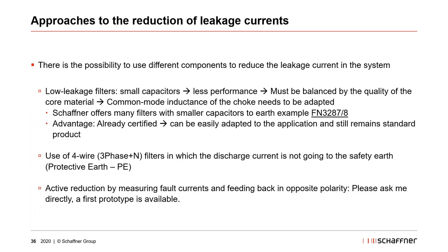Additionally, if you have the ability to use a 4-wire filter, then this might reduce your leakage current, not discharge current. This is a little bit of wrong wording. Okay. So 4 wires with the attached neutral will have not as high leakage current as others.